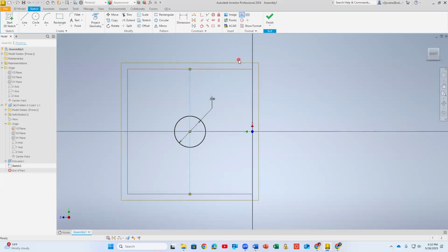So they said delete the lines that were projected on the sketch along with the center line that was used to create the circle. If after trying to delete the lines they're still visible, don't worry about them since they will not affect any upcoming steps. I don't like to use this because I know I still need them. They're part of my geometry because I'm using my constraints. I like my sketch to be fully constrained, so I would prefer to just select and switch them to invisible. I really don't need to delete them. They're now invisible, though I use them for something.